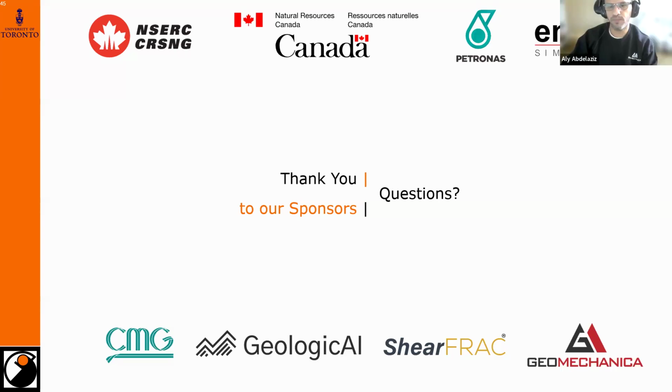Sure. So typically, if you are testing according to the ASTM standard or the ISRM standard, they typically advise that you reach breaking of rock between somewhere, I think, 2 minutes and 15 minutes, if memory serves me right. If you look at strain rates for typical rocks, that's somewhere between, I would say, 0.05 to 0.2 millimeters per minute.